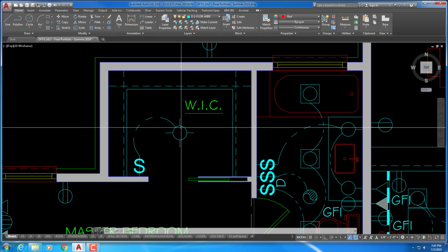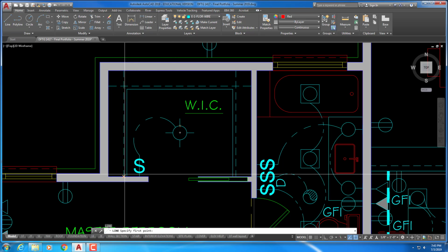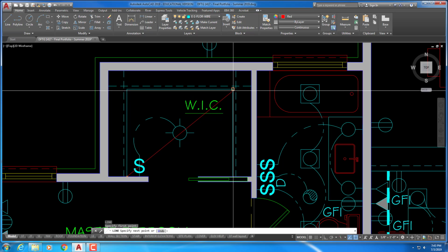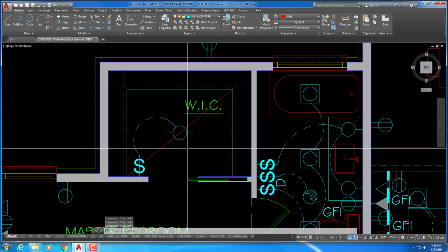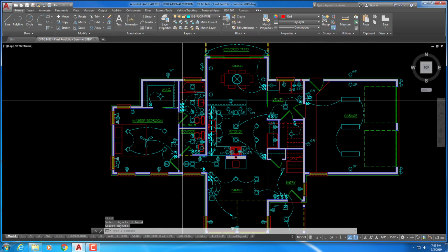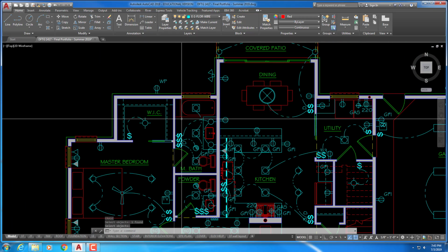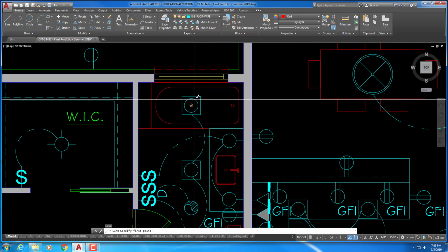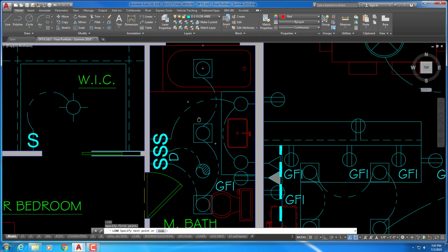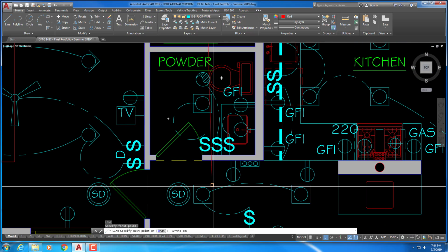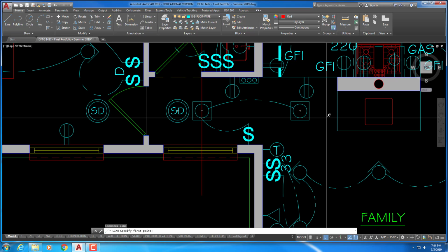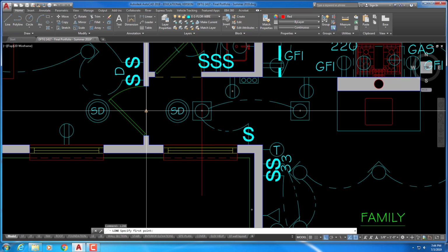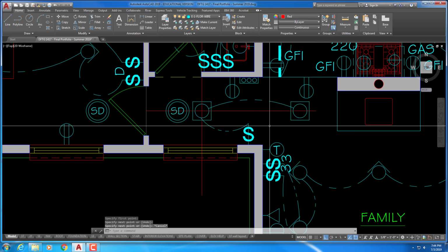For the walk-in closet, you need to center the light between the shelves, not the walls, so it's kind of pushed forward a little bit. At first glance, it may not seem like the fixtures are organized through here, but basically all those fixtures are based on the midpoint of the window all the way down. And then this is based on the midpoint between the walls here, which if the door is located correctly, will be the midpoint.